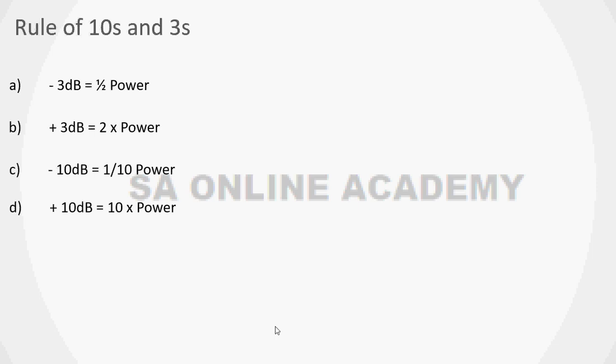You have to keep that rule in mind always to calculate your values for Wi-Fi, your loss, and your receiver sensitivity. As we proceed further in this video, you will see there are a lot of things: RSSI value, signal to noise ratio, receiver sensitivity. These are the values which you have to calculate for perfect design and implementation. You need to calculate free space path loss and any other loss in your network. All these losses have to be considered.